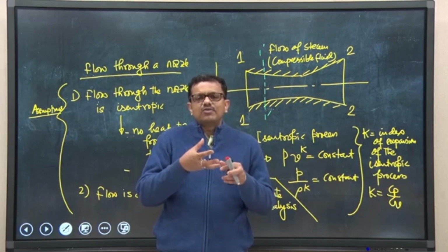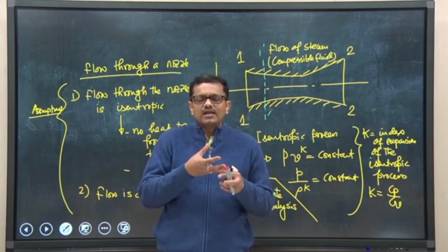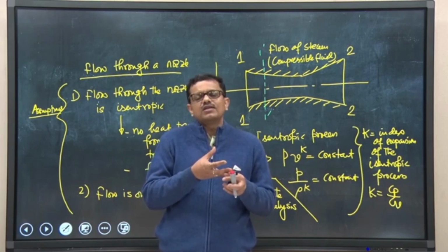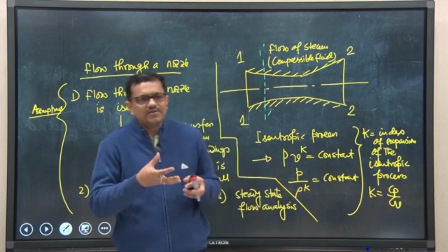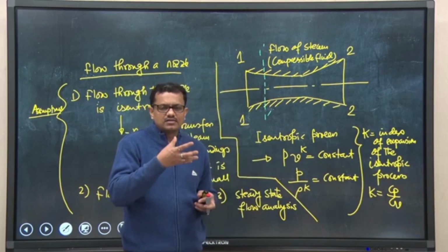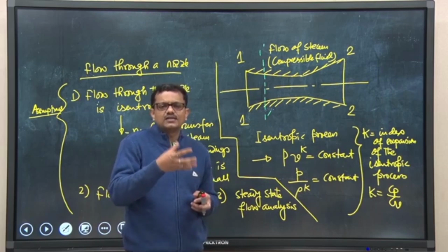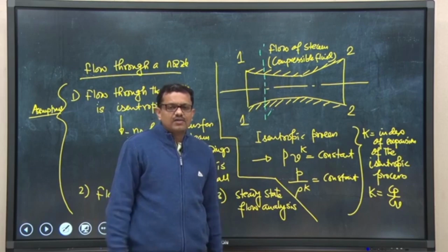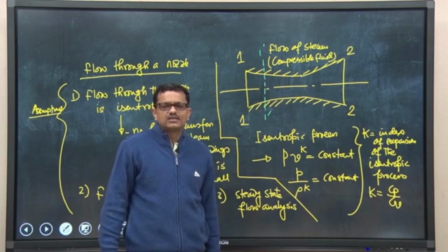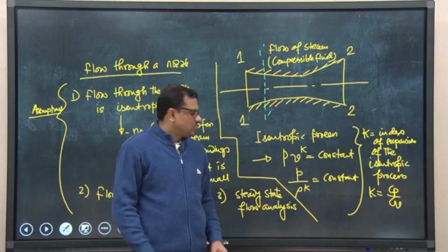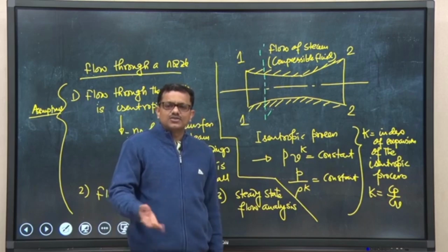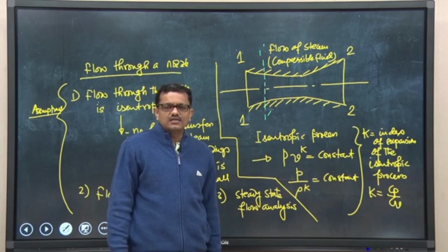The momentum absorbed by the turbine wheel depends not only on the steam velocity at which it impinges the blades and the blade angle, but largely on the velocity of steam we get at the exit of the nozzle. There are several other issues that we shall discuss.